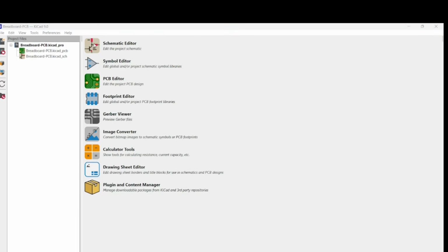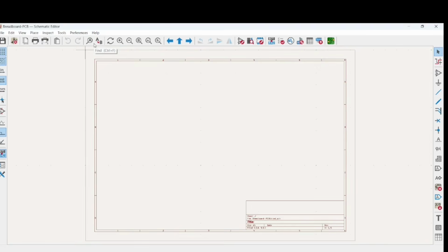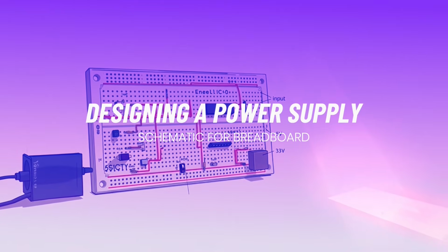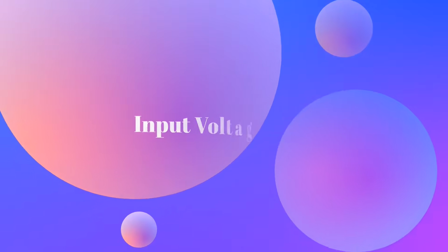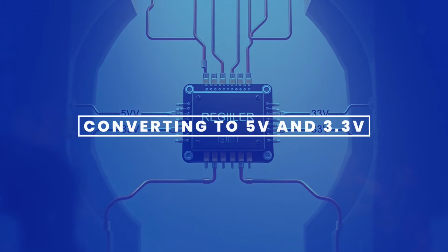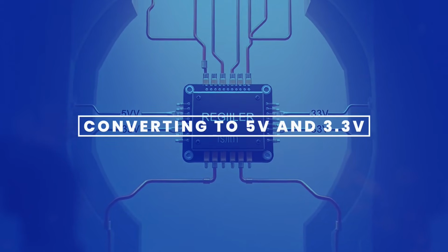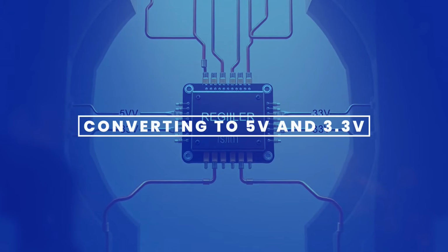We will now click on this first icon, which is the schematic editor, and let's start building our circuit. We will design the schematic for the breadboard power supply. So we have the input as 9 volt, which is the power, and we will use some regulators like 5 volt regulator and 3.3 volt regulator with some components like capacitors and resistors.